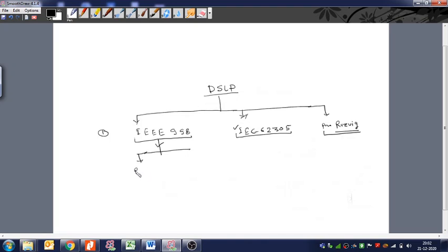First is the rolling sphere method. And second is the fixed angle method. The fixed angle method is very easy. We take a steel structure, which should be of higher height, or we can install another dedicated structure for this, and we place the lightning rod on this steel structure.